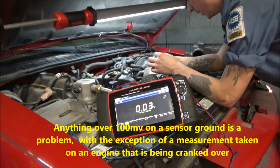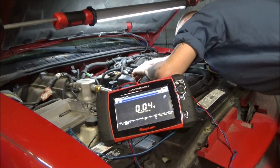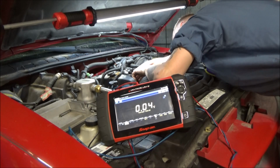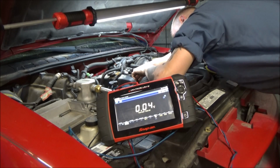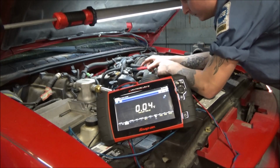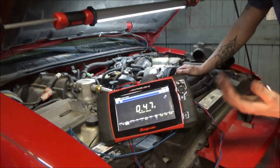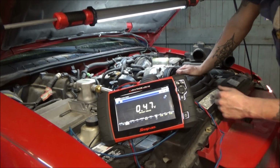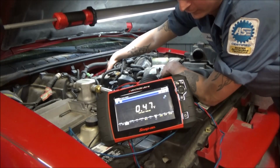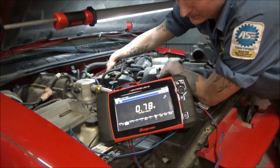So our last one that we really need to be concerned about here, guys, is the signal wire. I'm not sure what design signal circuit this is. I don't know if it is a pull up or a pull down signal circuit. I kind of want to say that it's a pull up, but I could be absolutely wrong. So obviously the key of the vehicle is on here, guys. We're just going to get an initial measurement of this throttle position sensor. We should be around that 0.5 voltage number that we had, and you can see we are. So I'm just going to re-execute this test on the signal wire, guys. I'm just going to slowly open this throttle plate, and we're going to watch this voltage.